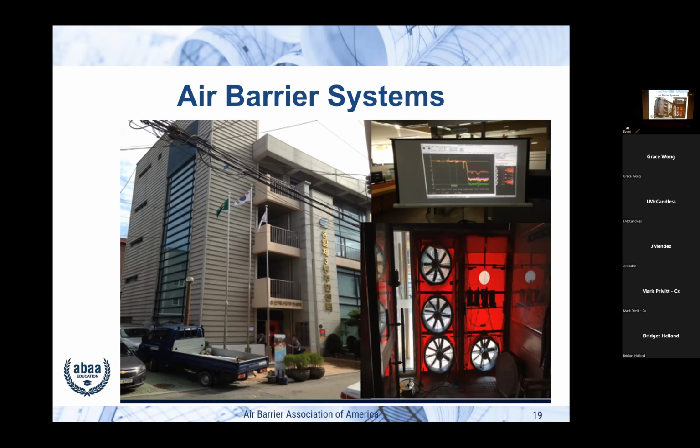Now, we do this all the time. We start to guess at where's the tightest and where's the most leakage part of the building. Third floor is a cafeteria. It's got equipment. It's got a duct that doesn't have a louver on, because you can't put louvers on exhaust vents where you got grease and everything like that going through it. So, well, that's going to leak like a sieve. Went up to the top floor. It's a classroom, meeting room, whatever you want. Not too much there, no demising walls, no nothing. That's going to be pretty airtight.